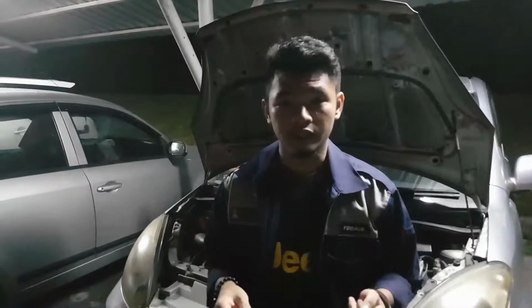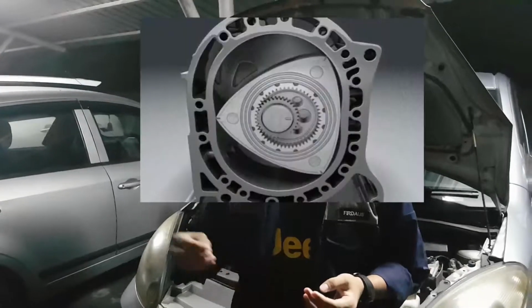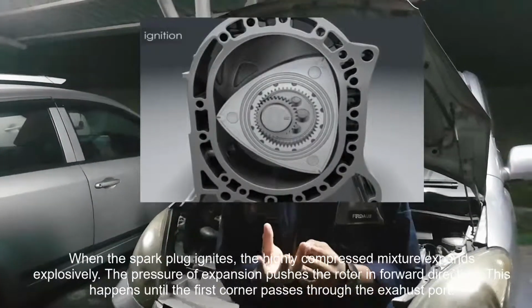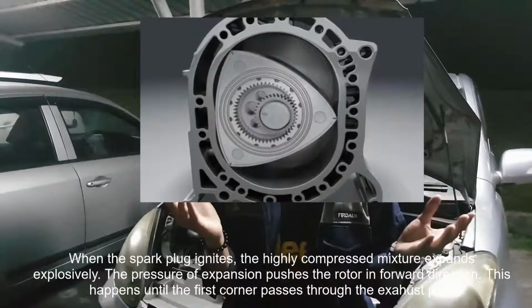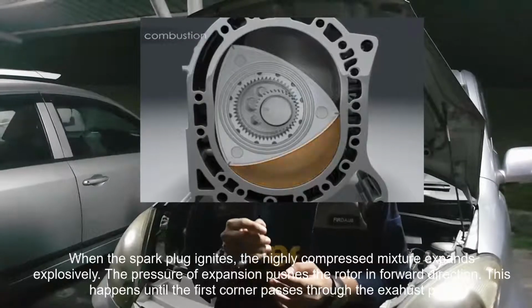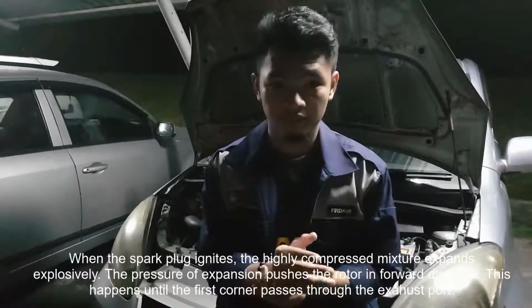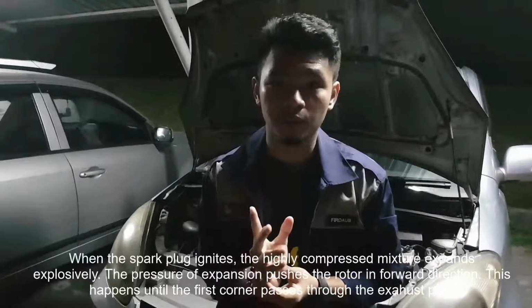Other than that, in the combustion part, which is the third part of the Wankel engine, when the spark plug ignites, the highly compressed mixture expands explosively. The pressure pushes the rotor in a forward direction. This happens until the first corner passes the exhaust port.